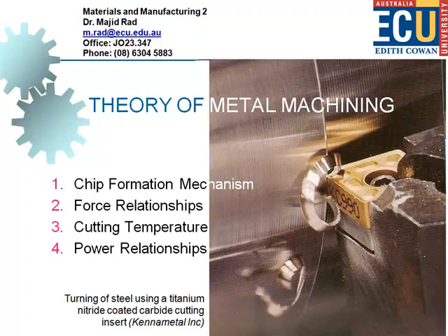Consequently, what we do is to make use of a material of lower quality to be used as the holder of the insert, and the insert will be inserted on it, which is of higher quality. Of course, we pay much more for this given material compared to the material which is used in order to make the holder. And carbide inserts of different grades are widely used in machining operations.